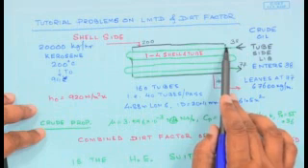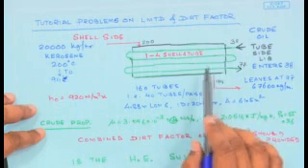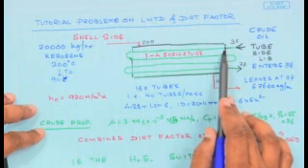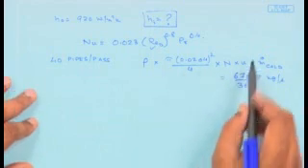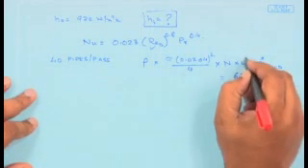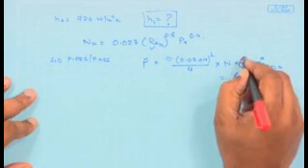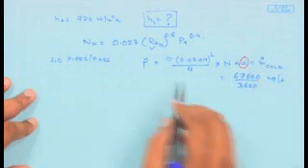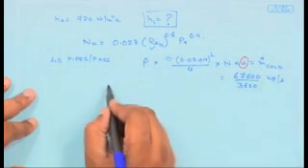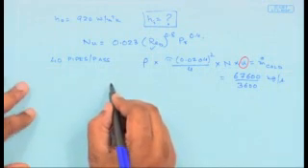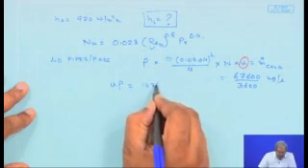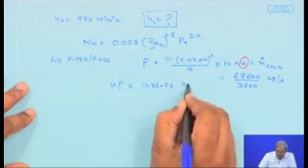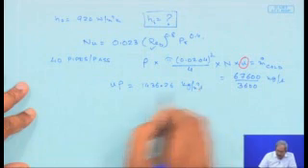Since there are 1-4 passes, there would only be 40 tubes available for this much crude oil to flow. So what I am trying to do in this case is find out this unknown velocity u for flow through the pipes. Everything here is known, so I would be able to calculate the value of u rho, which would be 1436.26 kg per meter square per second.